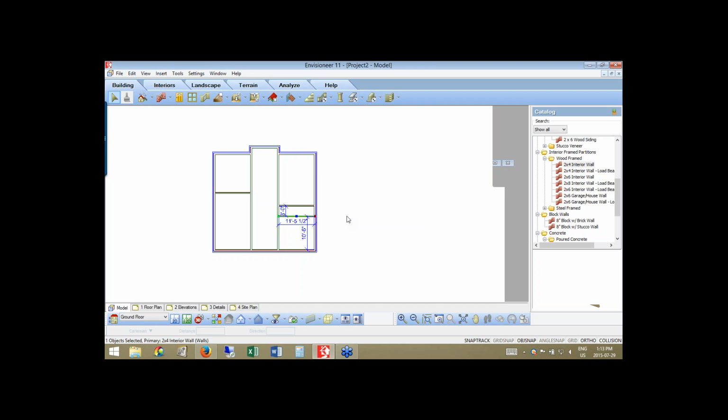Okay. Once walls are inserted, as they intersect other walls, they actually hinge off of those points. So you can see that one first very long interior wall that I first inserted. Now that I have those perpendicular interior walls running up against it and intersecting it, it's no longer one long wall. It sees itself as different pieces of wall. So with this one piece selected, if I hit delete, it's only going to delete out that one section. I just hit delete on my keyboard, and now that piece of wall is gone. The other portions there remain.